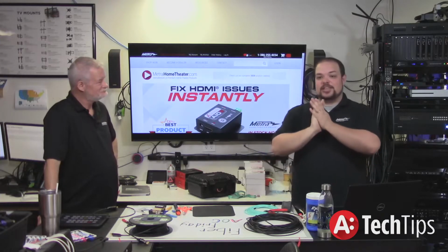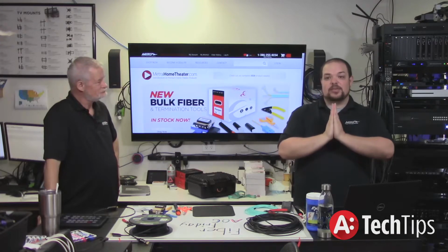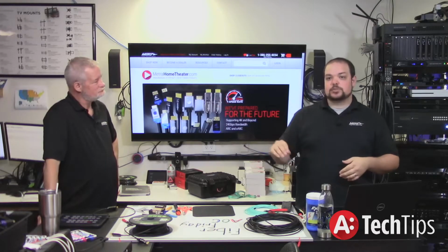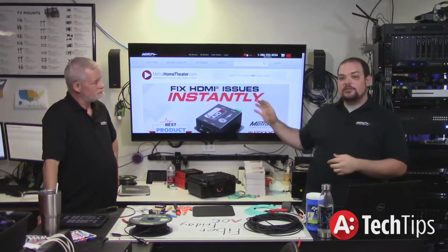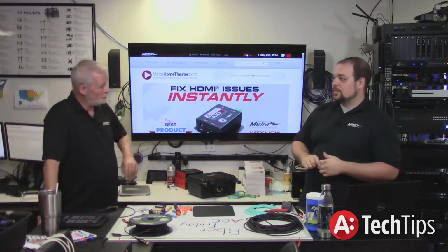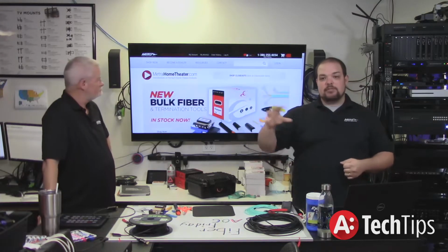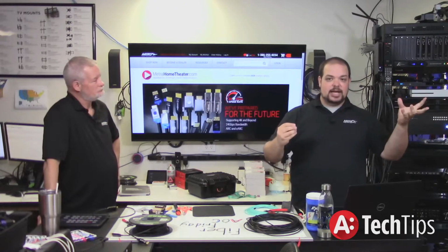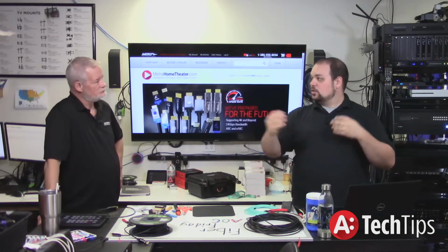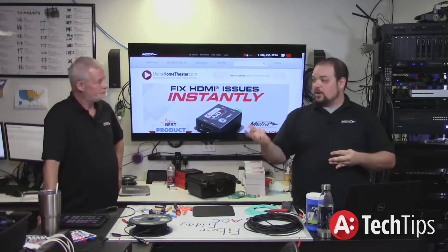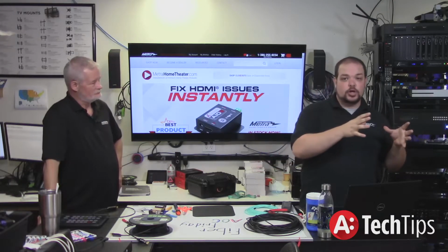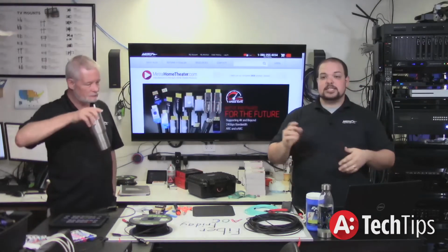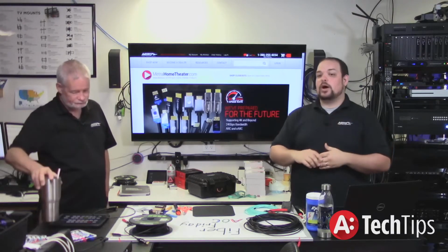So yes, the point of this is that when you have a standard copper HDMI cable, the TMDS are the actual lines or feeds of the video and audio going from the source to the display. Everything else is just information about the 2 devices talking to each other: I'm this, I can do this, I can display this. Those types of communications, voltage triggers, and all the different triggers are handled on the other low speed DDC lines. The TMDS lines are the high speed lines, where the bandwidth requirements are.